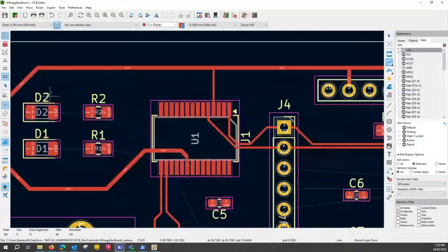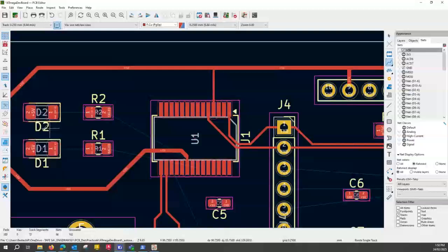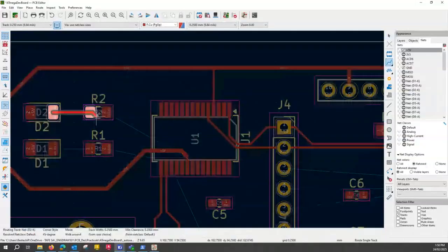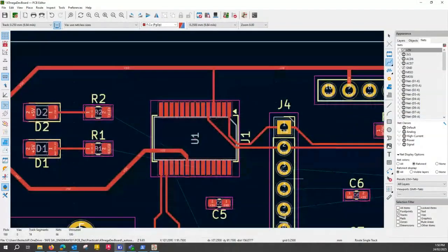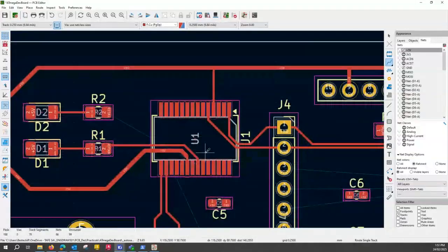And also, okay, I need to rotate those 2 because 5 volt is on this end, that connection goes here. So I'll just select that, press R twice, and now I can connect my pads. And now I have to run to those pins. So what I'll do is I'll run this across, and yeah, I can connect it right like this. That's not ideal situation there.